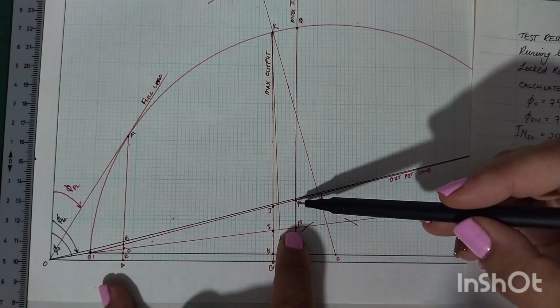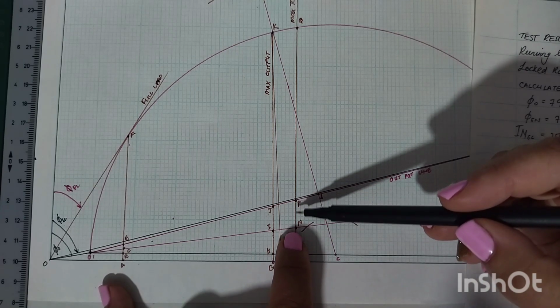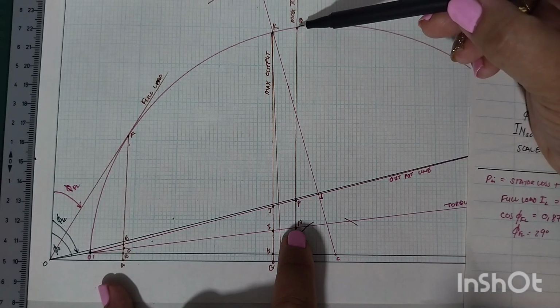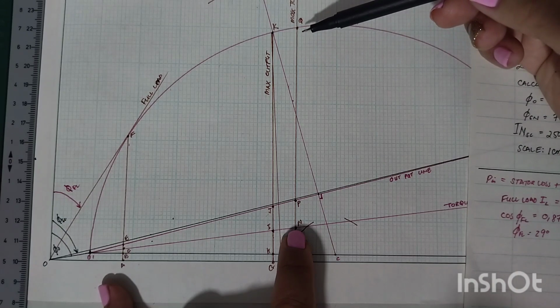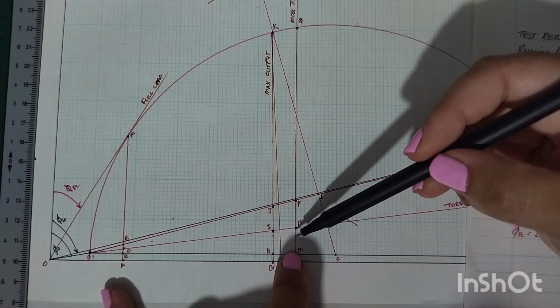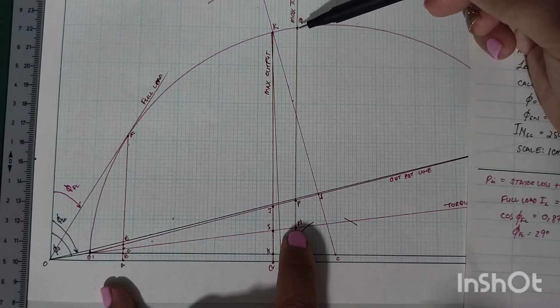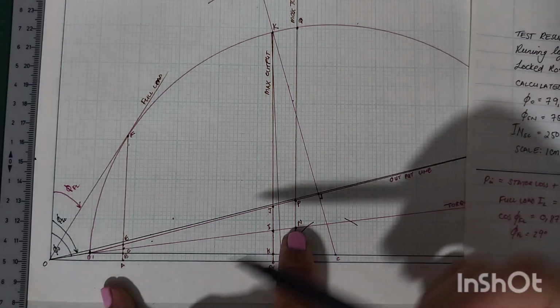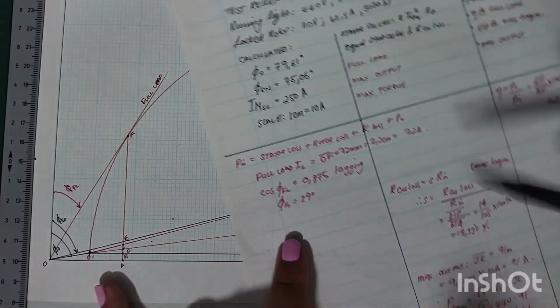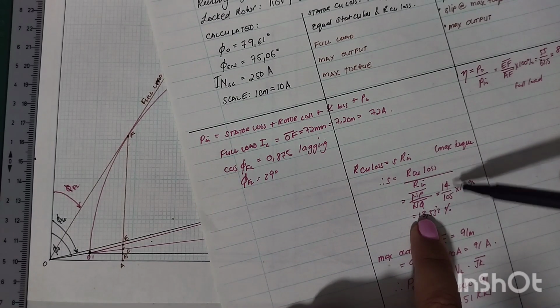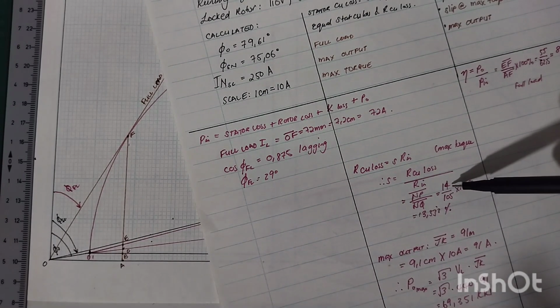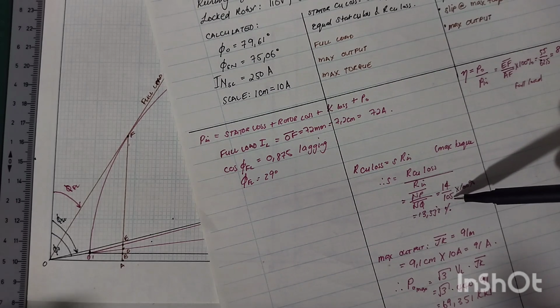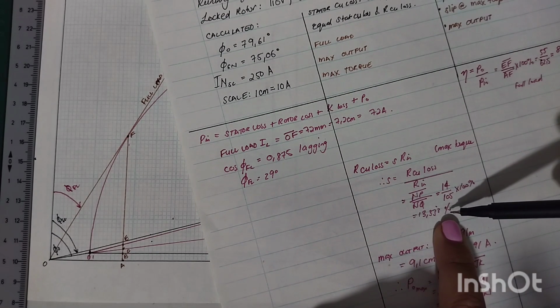So it is a ratio, slip. It compares your actual speed to your synchronous speed. In this case, it's comparing your rotor copper losses to your rotor input. So you don't have to calculate the associated power here. Just measure those two lengths, from your torque line to the perimeter of your circle and the distance between your torque line and your output line, and get the ratio there. And when I did that, I got 40 millimeters and 105 millimeters. That gave me a slip of about 13%.